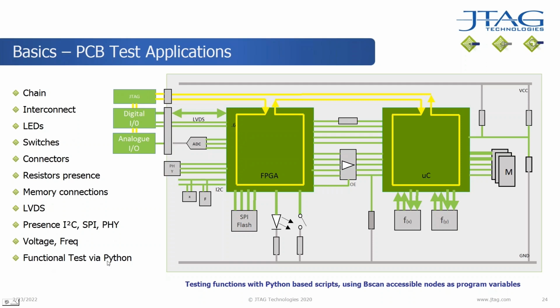But as well as that, there is some possibility to write scripted tests in a system we call JTAG functional test that is based on Python. Not exclusively based on Python, because there's also the possibility to create these tests using LabVIEW or .NET framework programming options as well. But Python is well liked and well used, and it allows us to create tests which involve not just a sequence of test patterns, but conditional branches and loops, and the sort of techniques you would associate with functional testing.